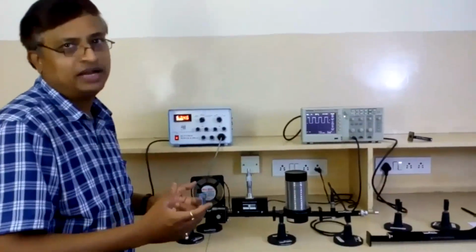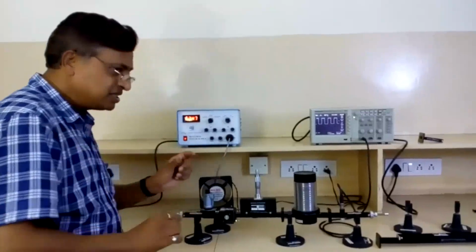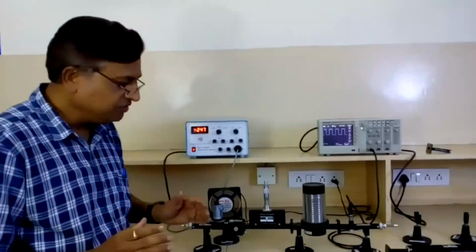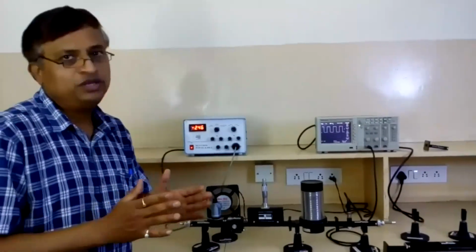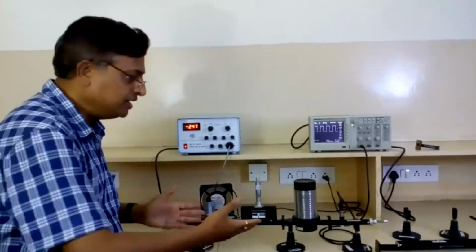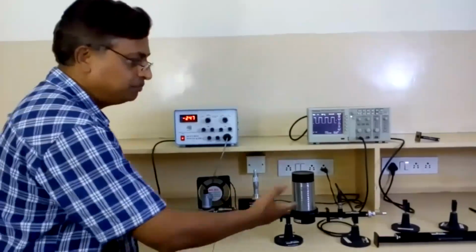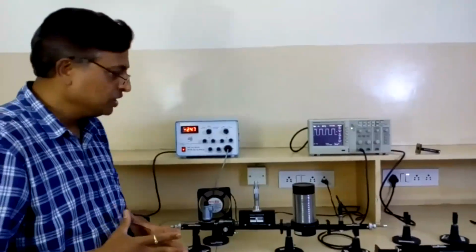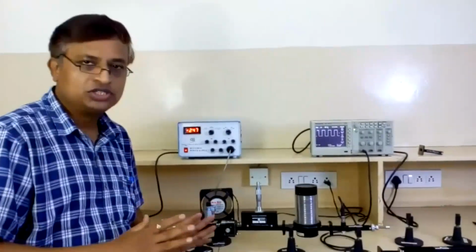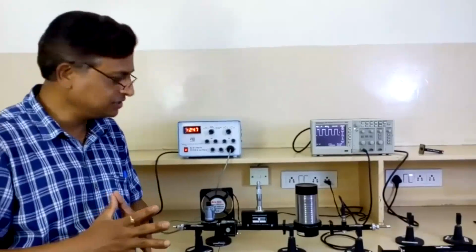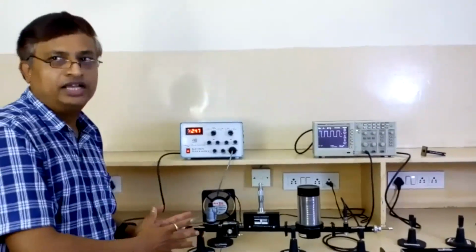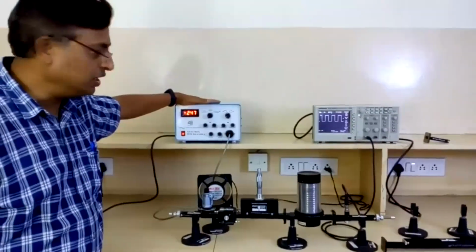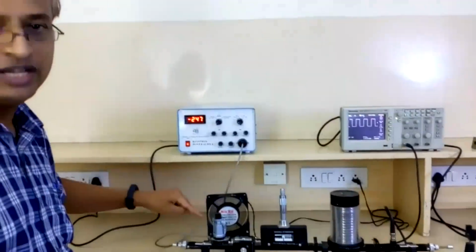designed for X-band setup. So as the frequency is huge, the waveguide size becomes small. If it is in the C band, it would be a large size of waveguide, and then it will be difficult to have the setup and the total measurement. It becomes a tedious job. So for laboratory observation and verification of the microwave devices, particularly X-band is preferred. So the power supply setting we will understand now, which we need to bias reflex klystron.